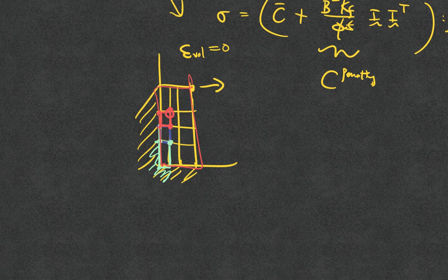It happens a lot when you have an incompressible material and you want to model bending. You would also see that the bending is incompressible, but strictly speaking, bending locking and volumetric locking are different things. It requires a different type of constraint. Now if you use a linear finite element, what are the options to get the whole deformation working?